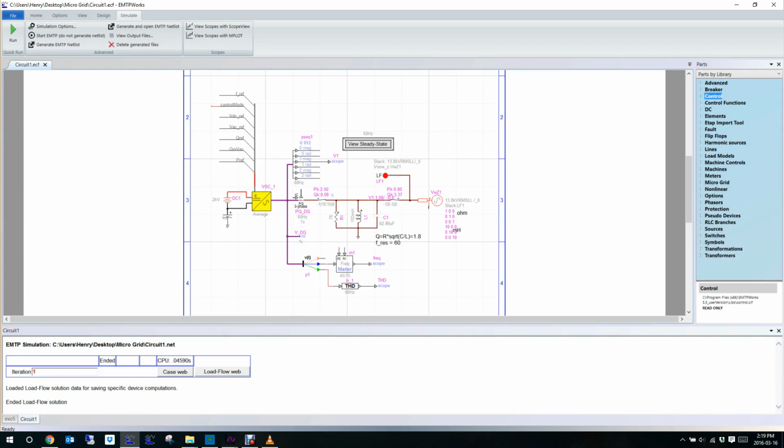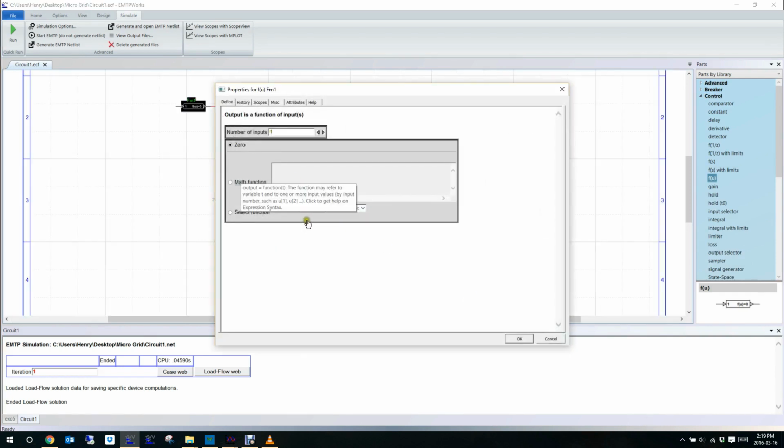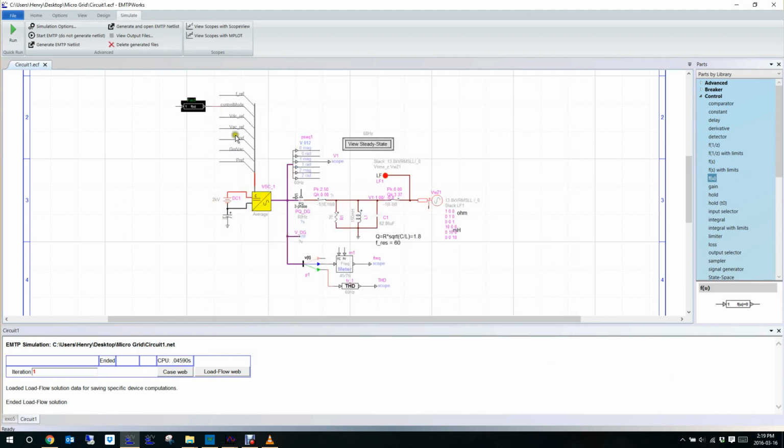here in the library control the function of U. And in this function, you can write your own mathematical equation, and you can use the time for that. So what will we say? It's 1 plus 3 multiplied by (time larger than 0.5). Here, the condition t larger than 0.5 is 1 when it's true, and 0 when it's not true. So in the end it's 1 plus either 0 or 3, so 1 or 4. So we are good here. I don't actually need an input for that in that case.